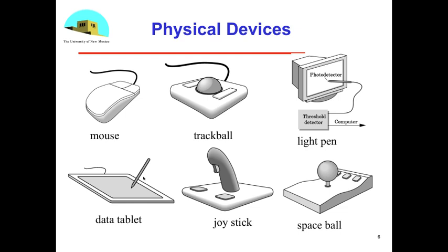So let me talk a little bit about each one, and let me start with the light pen. The light pen was actually not a device that wrote, it was a device that read. You had a stylus that had a photodetector in the tip, and so it could see the beam on the CRT. If you look at the properties of a CRT, which you talked about a while ago, it emits light for a very short amount of time, and it's very bright for an instant, and that's how you set the detector in the light pen, and it detects that.